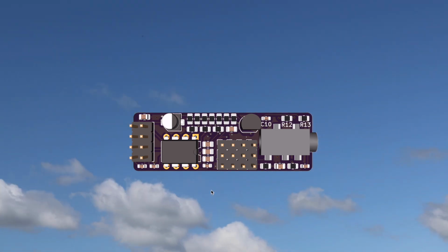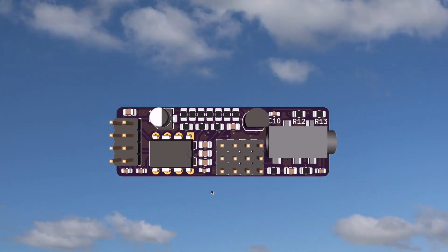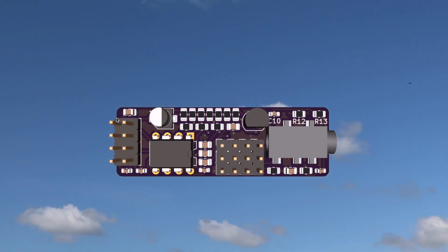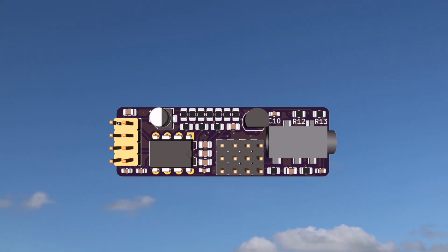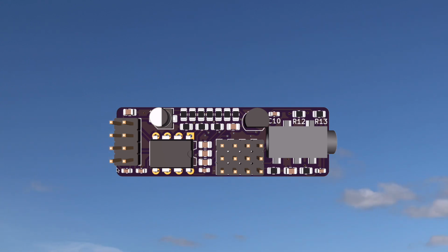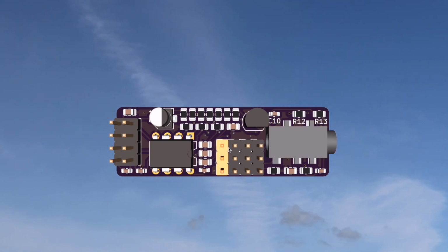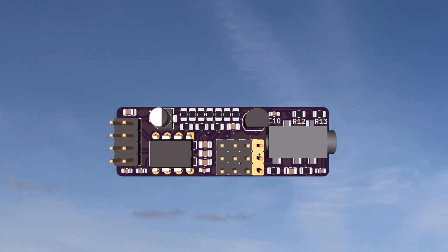This is my simple universal modem design. You simply connect 4 jumper wires from your microcomputer, Arduino, and so on to the data in, data out, 5 volts and ground on the left side, and connect a 3.5mm mini jack cable on the right. The pin header jumpers here in the middle are for selecting which of the cable lines are for input, output, and ground.